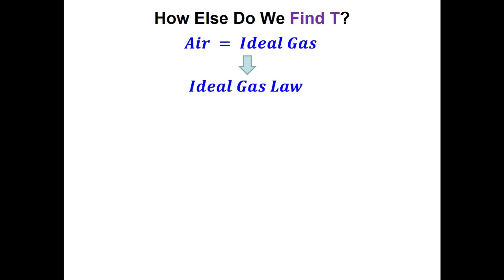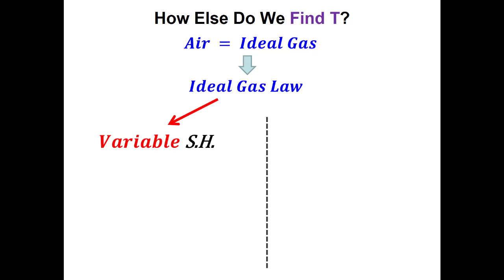Now this is the first cycle that we've looked at where we have ideal gas or air as the working fluid. But when we do this, it's really important that we recognize which processes are isentropic. So when we have an ideal gas, remember, the what's-the-fluid question is always a two-part question. If this was water, we would first say, oh, it's water. And then we would say, what's the phase?